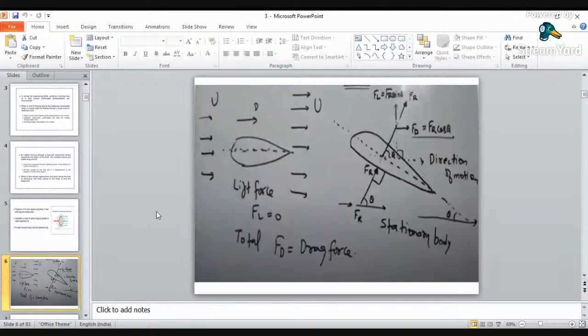Okay. One application where the buoyant force is addressed is floating bodies. In order for a submerged body to be stable, the body's center of gravity must lie below the center of buoyancy of the displaced liquid. In order for a submerged body to be in neutral equilibrium for all positions, the body's center of gravity and buoyancy must coincide. That is, the buoyancy force point and the location of the center of gravity should be the same if it is in an equilibrium condition, with no submerged condition or no drag condition.